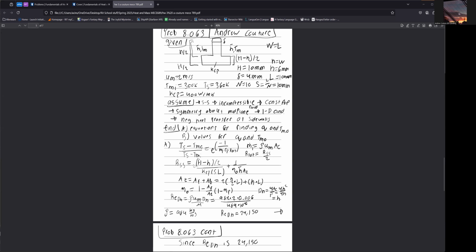Continuing on, the RSS equation is the heat resistance. So we're essentially doing heat resistances across the surface rather than doing each individual thing individually. We're just totaling up the resistance of all of the separate tubes together and then doing those calculations out. Which is also why we need the efficiency for basically everything, which is from the efficiency for the fins individually.